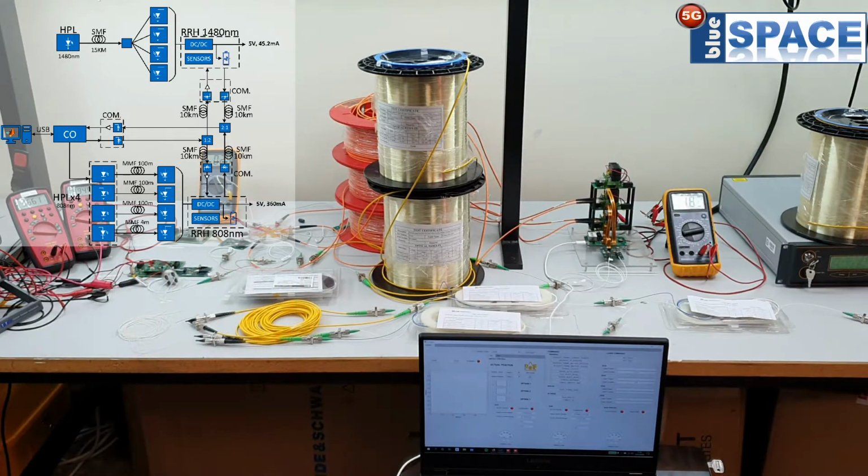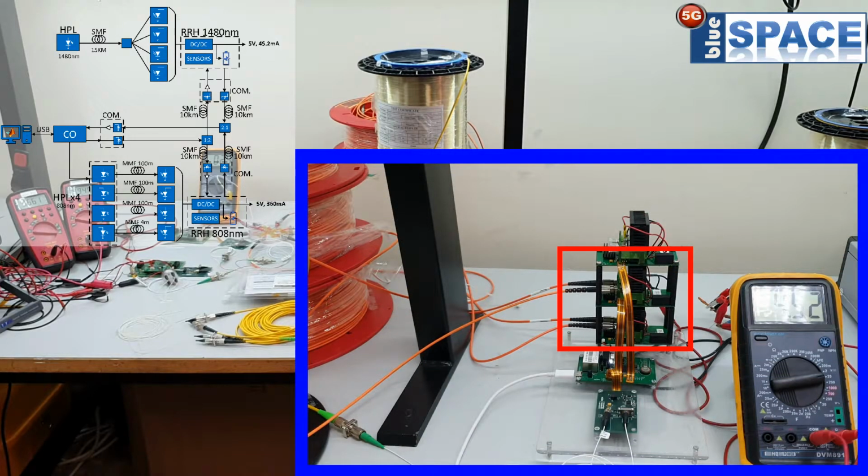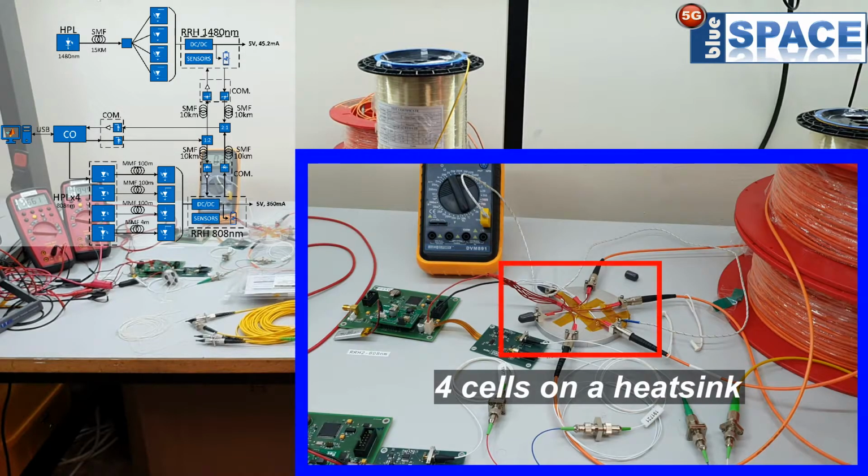The 808 nanometer system is made of 4 808 nanometer high power lasers, 4 different multimode fibers with different lengths, 4 cells located on a heatsink, and another RRH, also able to communicate with the central office through two 10 km single mode fibers and a communications board.